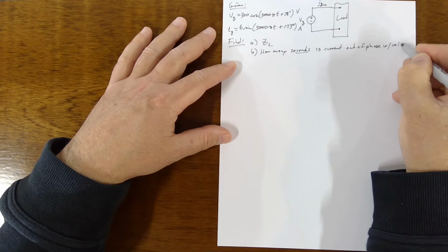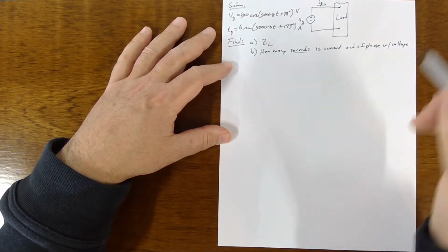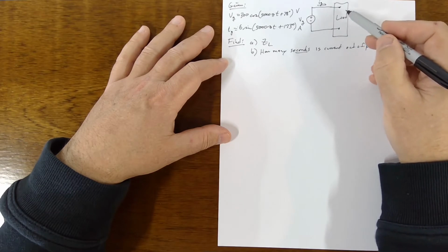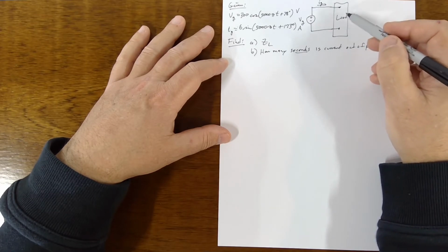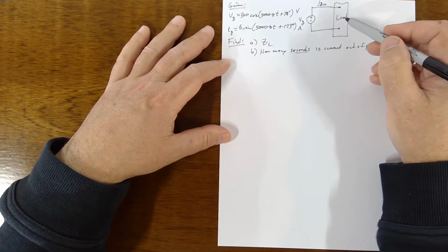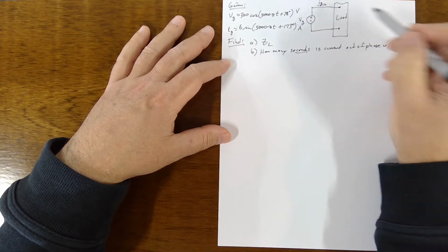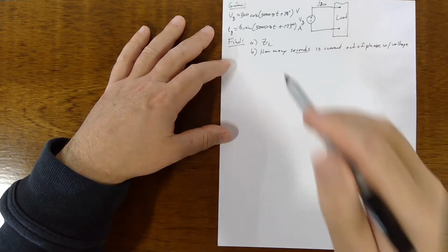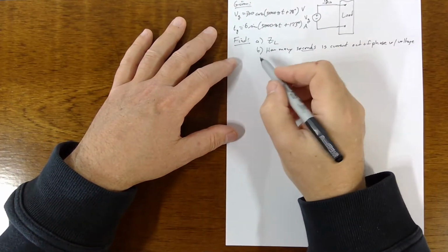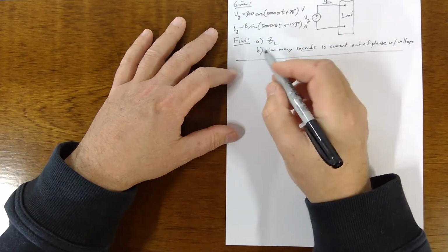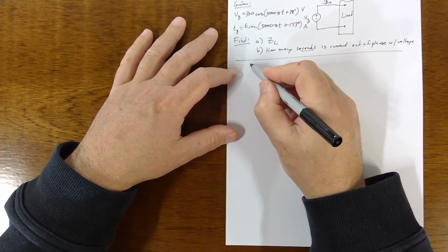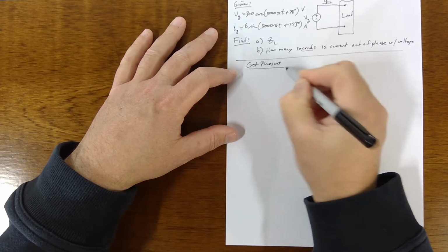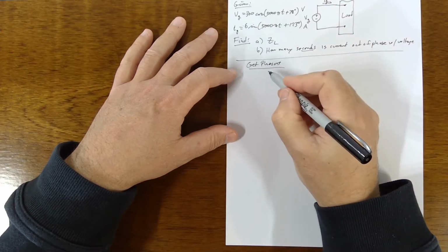with the voltage. Because if this is a reactive load at all, if it has some capacitance or some inductance, then the voltage and the current will be out of phase. If this were a purely resistive load, then the voltage and the current would be in phase. So we have to determine Z sub L and see what's going to go on. So we'll just get our phasors. Transform to the phasor domain, the frequency domain.